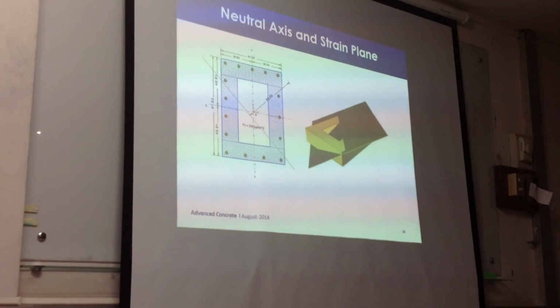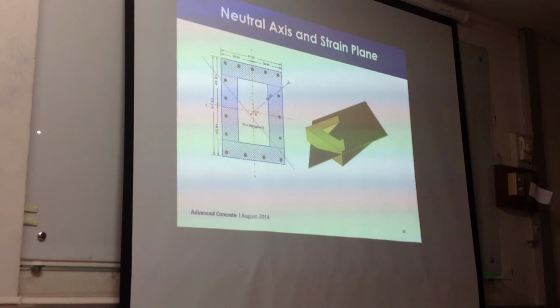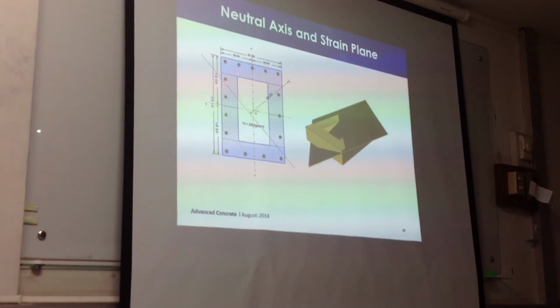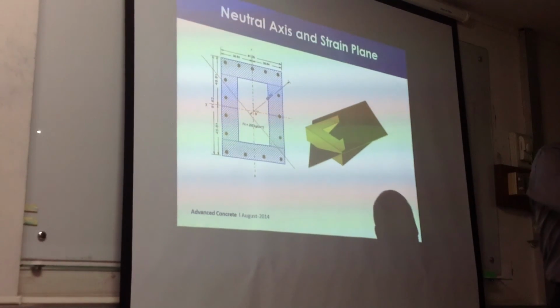I can calculate the stress from that profile and I can continue. So our theory, our equation, is not affected by any of those assumptions. It does not assume plane sections remain plane. It does not even assume perfect bond between concrete and steel, because each material can have its own stress-strain relationship offset by something.